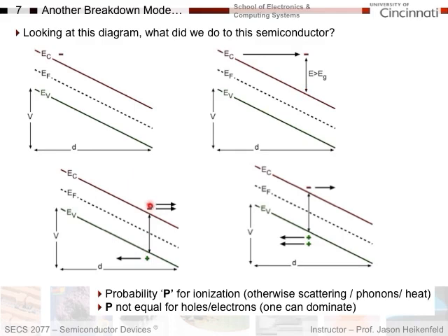That means the electron came down, gave up its energy to the silicon, causing thermal generation, or in this case, direct energy generation, of an electron which is kicked up from the valence band to the conduction band, which also creates a hole. So now you can see this multiplication where one electron got enough energy to create two electrons and a hole.